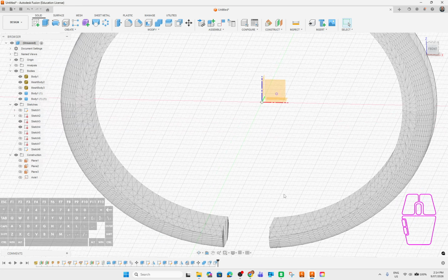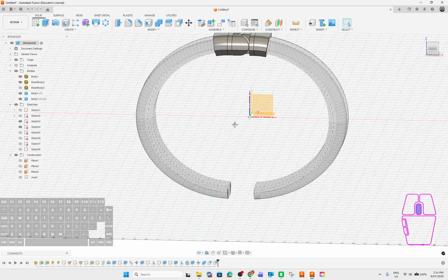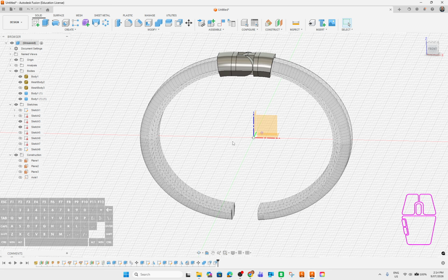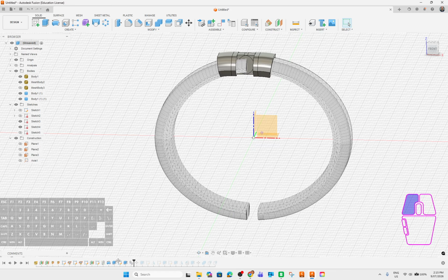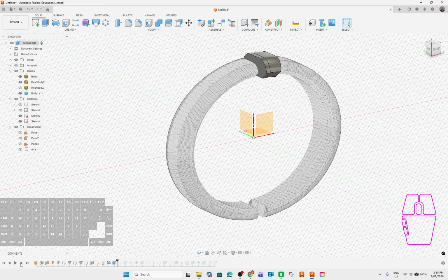Now what I need to do is turn my attention to a clasp here, so something that kind of goes together and fits in. There's a number of different designs that I could choose, that kind of thing. And again, I'm going to use that same technique of copying out the body because I know that this is going to be the same as this body here. If I go back in time to where I've made that body, I should be able to slot in a little copy out, a little mirror of that component, so work off something like this. So I'll wait and see till I've got it the way I want it.